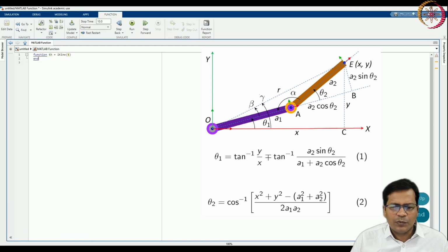Okay, what I am going to do here, I will insert a trajectory at the end. Okay, let us say I want to have a circular trajectory for the tip of the 2-link manipulator. Those positions I will keep on pushing to the inverse kinematics function, and in turn it will give me the joint angles. Okay, so if I feed that joint angle to the joints, it will start moving, the end effector will start moving in a circular trajectory that is planned.